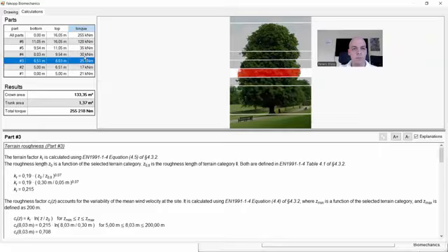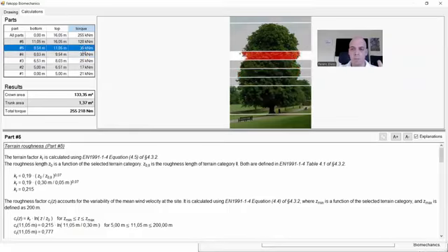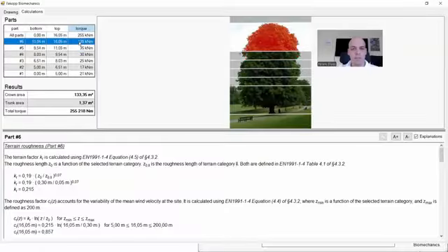It is very visible that as I go upwards, the basic wind velocity in the standard has different multipliers depending on the height, and each layer here has a wind velocity. And this wind velocity is used from the top of the layer. So there are several things in the standard that go towards overestimating the wind load. As I go upwards, you can see that the topmost part is taking most of the wind and most of the torque is coming from there.